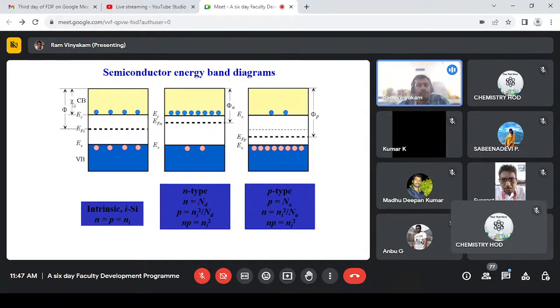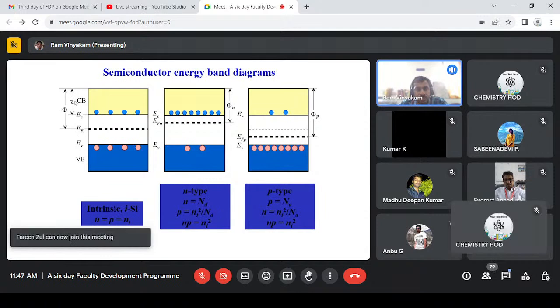Or in the case of a semiconductor, we refer in terms of electron affinity. The Fermi energy will be fixed in the case of metal, but the Fermi energy in a semiconductor is purely an imaginary thing. There is no actual electron in the Fermi level. So we take electron affinity when we want to compare the band structures of different semiconductors, or with metals or different materials too.